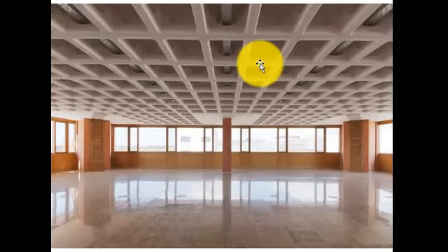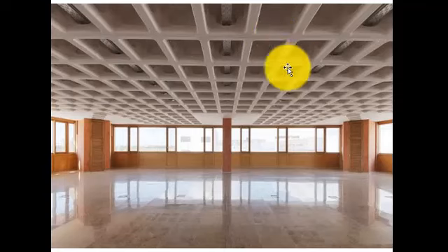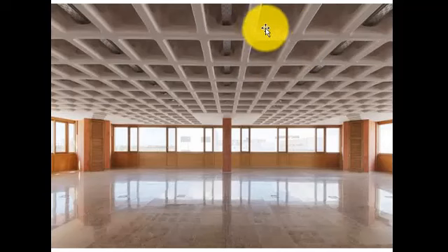The second type of slab we have here is the waffle slab. You see, a waffle slab is a slab with holes beneath it. You can see the holes beneath it. So it is now giving it an appearance of a waffle, or something you can call a grid. Some texts refer to it as grid slab instead of waffle slab, or they just say waffle slab or grid slab. So you can see it here.